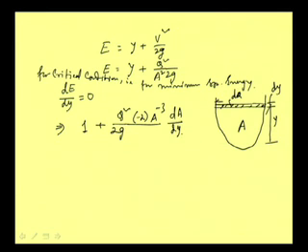Then if I write this as the top width T, from here to here, then this dA is nothing but this top width into dy. Rather than going for differentiation on all these things directly, we are writing in a very straightforward way from the actual figure. So, dA is equal to T into dy, or we can write that dA/dy is equal to the top width. Well, so by replacing this term, what can we have?